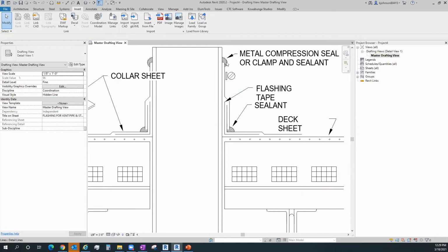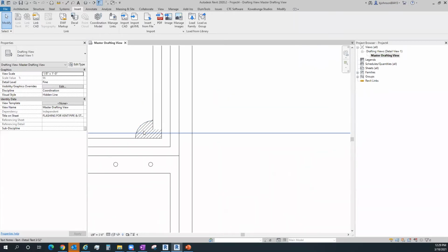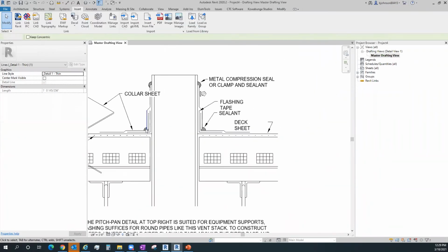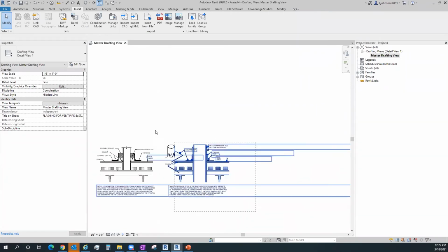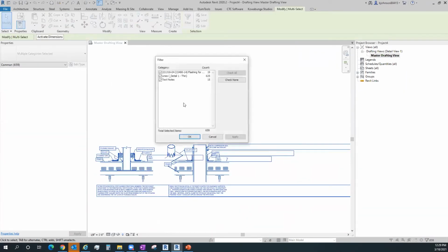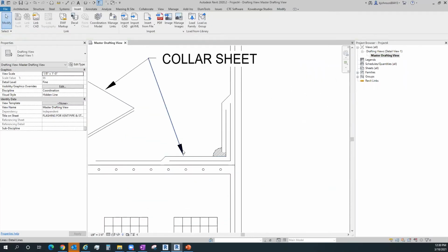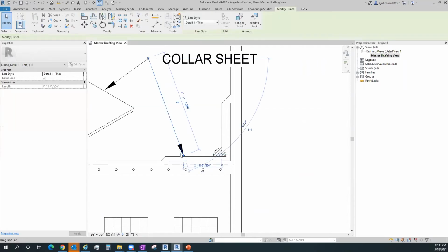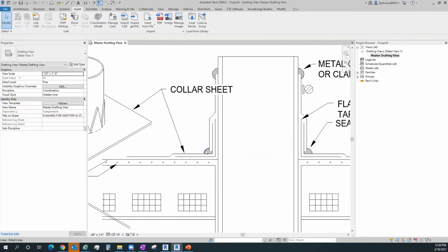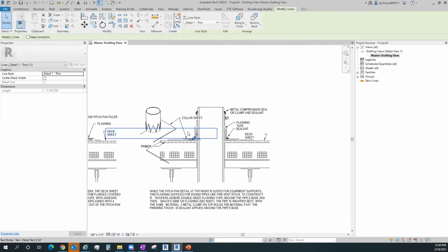And every time I see that there's one of these objects, I need to find out, is that still an explodable object of its own, or is it just line work again? So if I do a selection set and filter, I can tell by this name right here from the drawing name, there's still 19 things that I did not explode that I need to either filter out or do something with. Some of those will be the arrowheads. Probably the majority of them will be arrowheads, but every once in a while there'll still be a fill pattern that I need to change or swap out.